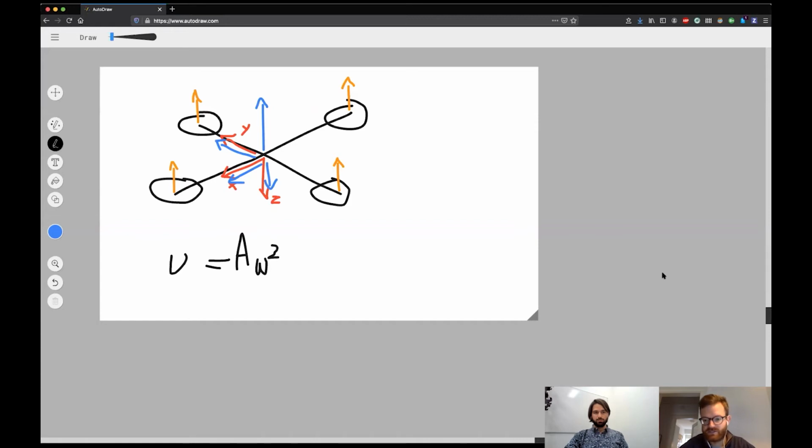And because the question just came up, the thrust is always perpendicular to the rotor. Yes, the thrust produced by each rotor is always perpendicular to its blades, basically. Then we want to find this linear relationship between u1, 2, 3, and 4, and the rotor speeds. So we also have to find a numbering for all the rotor speeds.